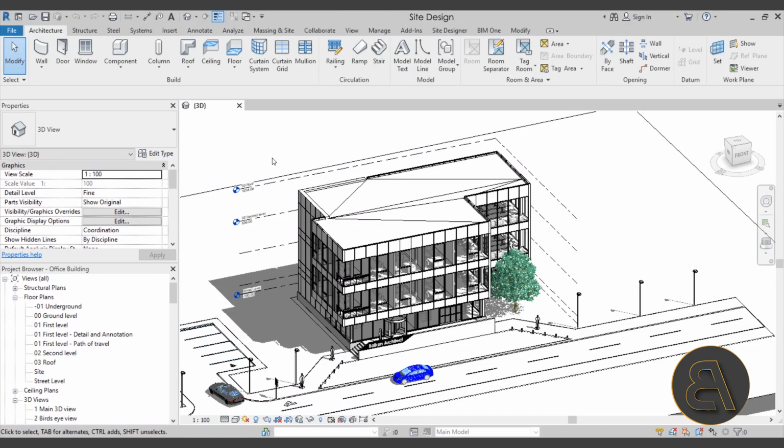The first level on which you can affect the graphics in Revit is going to be the program level. So when I say a program level, I mean basically the version of Revit that you have installed on your machine. So if we make any changes on this level, it's not only going to affect the project that we have opened up, in this case this project here, it's not only going to affect each view in this project, but it's also going to affect any other project that we open up in this particular version of Revit on this particular computer.